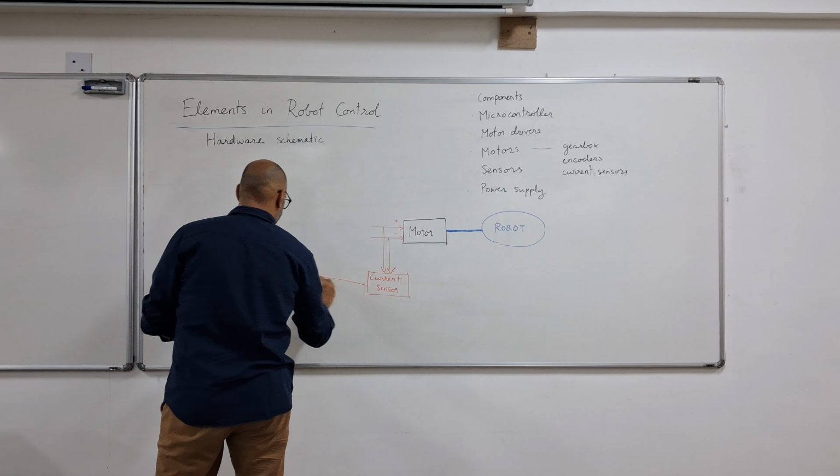And the simple answer for that is, the simplest way to think about it is, microcontrollers operate in low voltage regimes, whereas motors you typically need higher voltages, and motor driver is a translator in between, where it's looking at what are the decisions taken by the lower level microcontroller, but pulling higher voltage from a power supply and then supplying it to the motor.